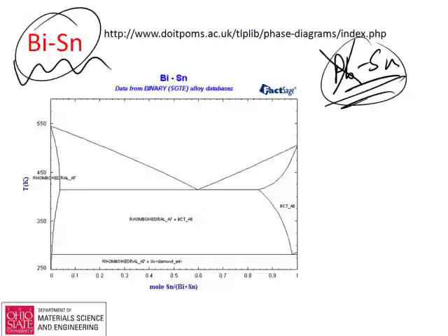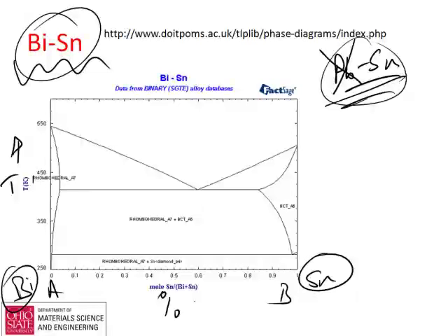But you can solidify bismuth on its own, or in this phase diagram, you can do some nice things with it as well, as we'll see. So on the phase diagram, this axis is temperature. In this case, it's in degrees Kelvin. This is percent. You usually go from A to B. In this case, you're going from bismuth to tin, and this is usually in weight percent. In this case, it says mole percent. You can do it either way.